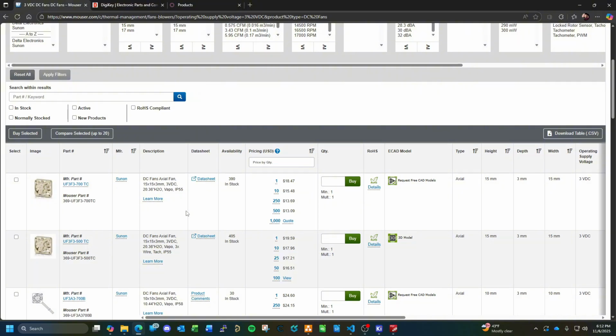I don't like relying on passive cooling with devices like this, because if that stepper motor is being used in continuous duty, that stepper driver will heat up, and I want to eliminate the possibility of it going to thermal shutdown as much as possible. We're going to use 2-ounce copper, which will help mitigate heat. We're going to have a heat sink on this guy, but active cooling, there's nothing wrong with it.